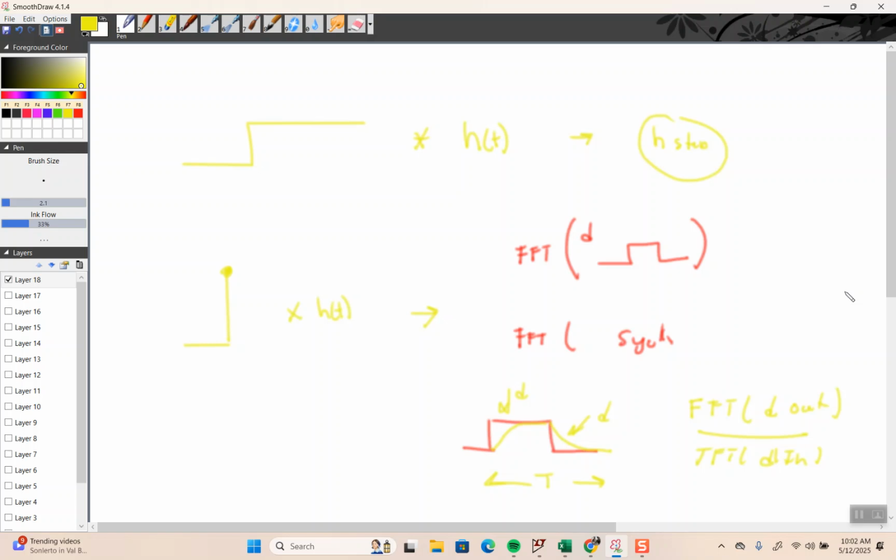It doesn't have to be one sine wave after the other, because a random signal over time will have all the frequencies in it. You just have to wait. But the delta function, when you take the Laplace transform of that, does have all the frequencies. The Laplace of a delta is 1. So it's all there.